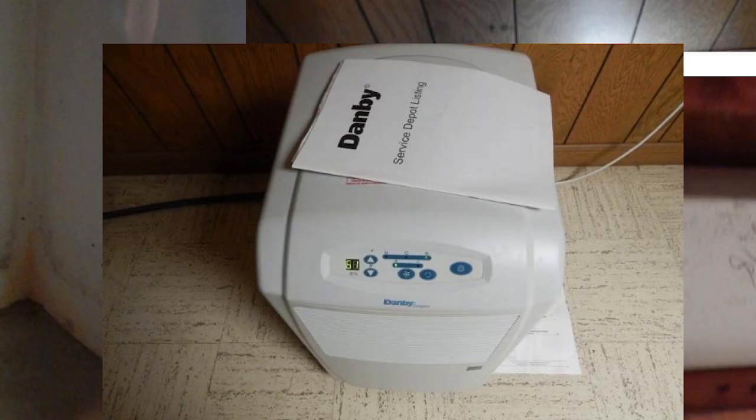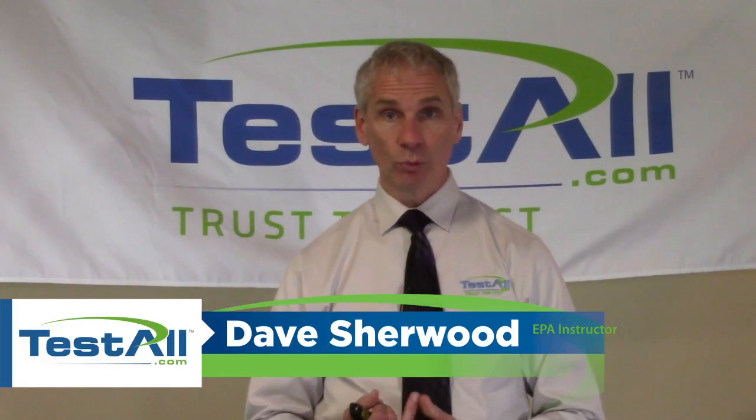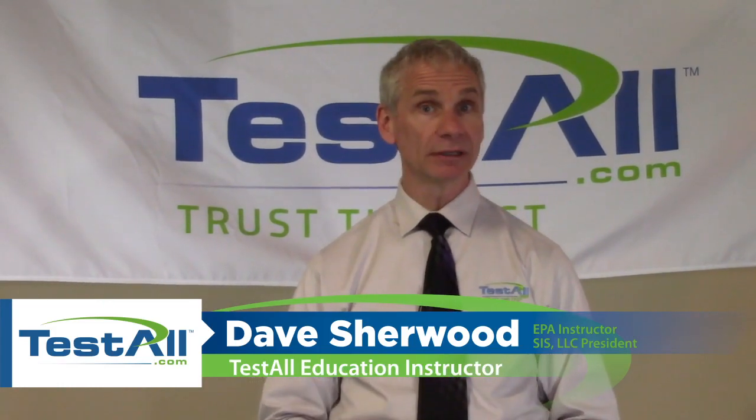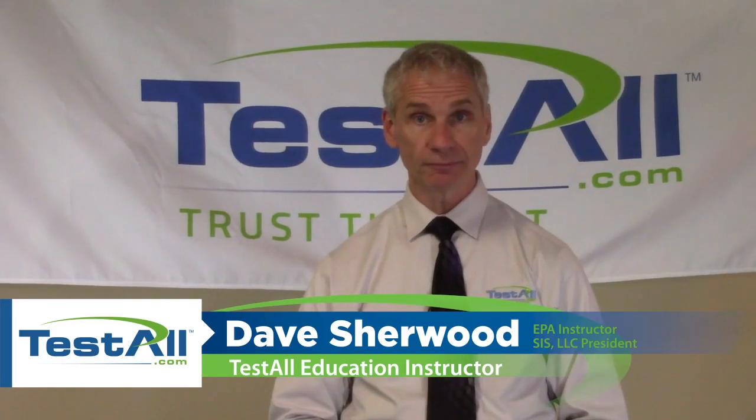And the next photo showing our handy dandy dehumidifier. Look at the setting. It's 67% and it's running constantly. Dehumidifier is too small for that environment, not able to correct the problem. So we now know where the moisture is coming from. We know that the moisture is still present in the air because relative humidity was over 67%.